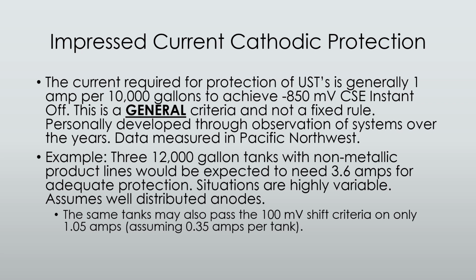If we were to adjust to a 100 millivolt shift, I have seen historically that about 1/3 of an amp would be enough to protect a tank and shift it 100 millivolts to get us to meet criteria for that as well.